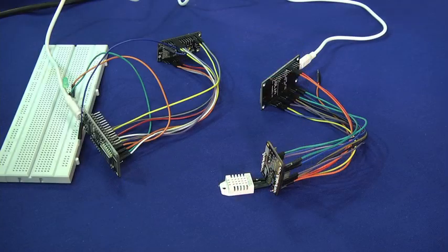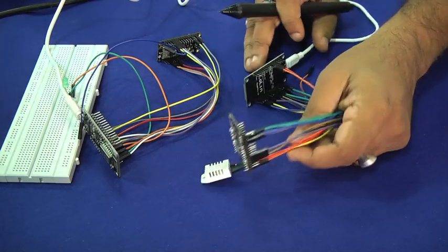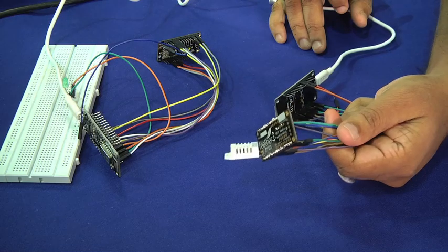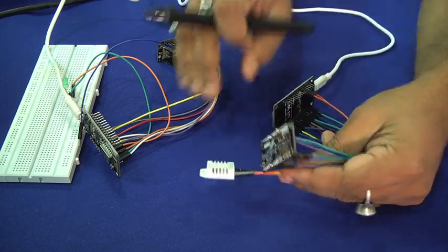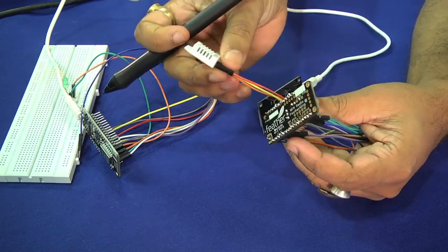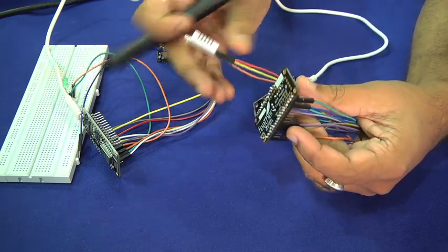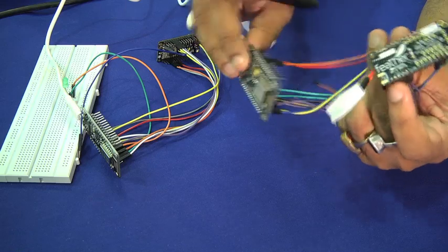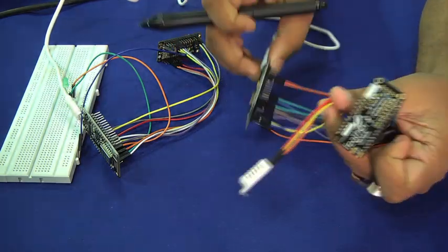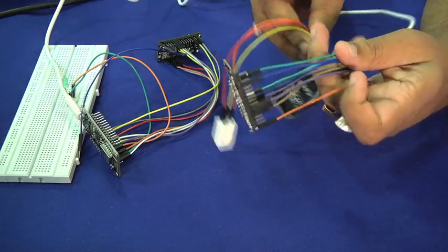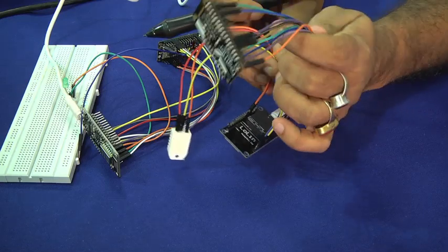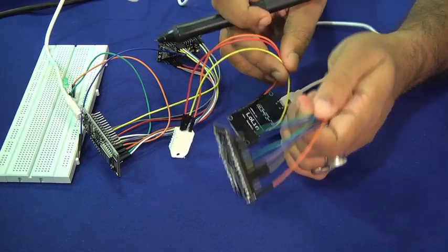So, now let us go back to our original setup. If you recall, this is what we have as our transmitter, and this is our temperature sensor, the DHT sensor, and their corresponding pins. This temperature sensor is connected to this NodeMCU, and the corresponding pin configuration I had shown you in the slide. And from this NodeMCU there is a connection to this LoRa transmitter, and this connection also I have shown you in the slide. So, you can try it out yourselves.